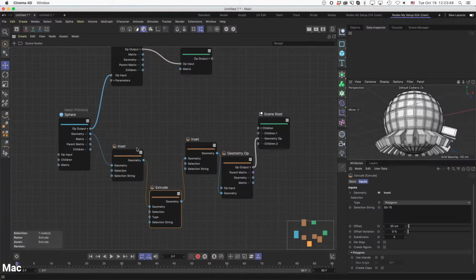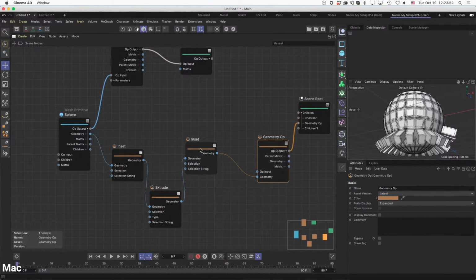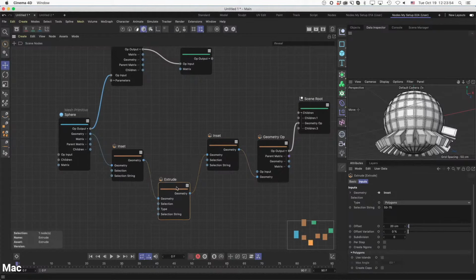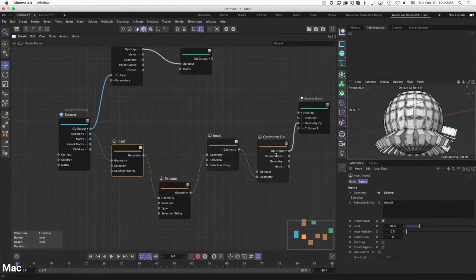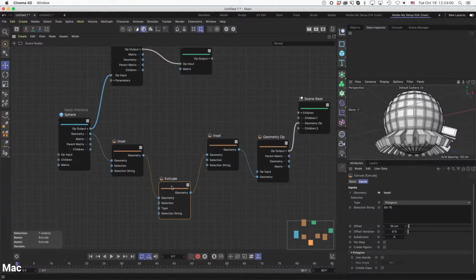And this is something that needs to be clarified. If during your modeling stream you tell a node to do a specific operation on a selection, not by name, because nothing exists by name here, there's no named selection, to any number of components, that does not become the active selection. So the active selection is whatever came out of here.